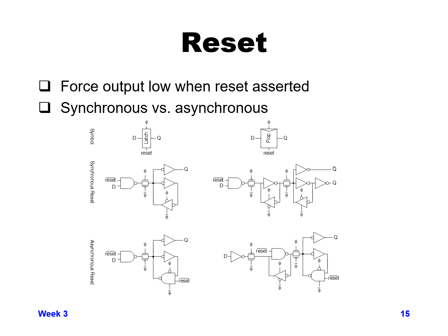Similar thing on the master-slave flop. You'll have the reset value going in, either into the master element, where you replace an inverter with a NAND gate and reset bar, or in the slave element, where you have the tri-state feedback replaced by a tri-state NAND gate with reset bar. And again, no matter what the value of clock is, you're sending through a reset value, whether clock is sampling or whether clock is trying to hold its state in the slave element.